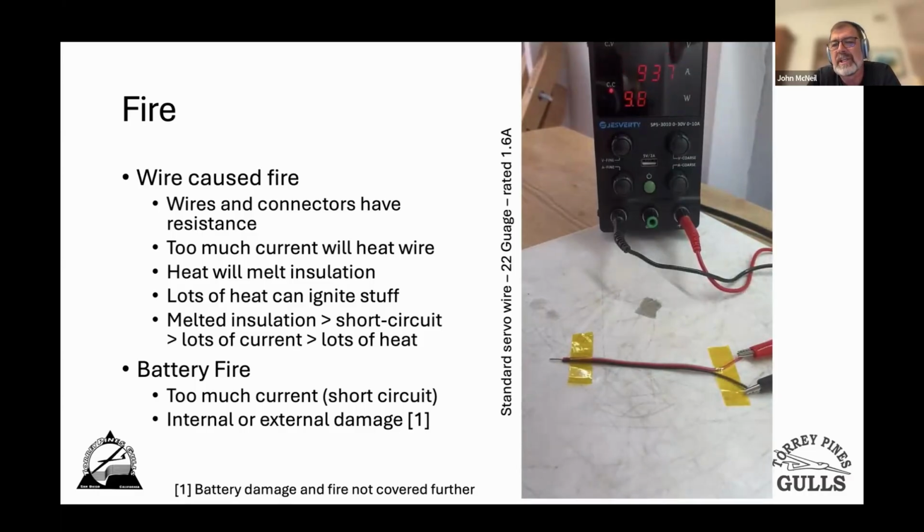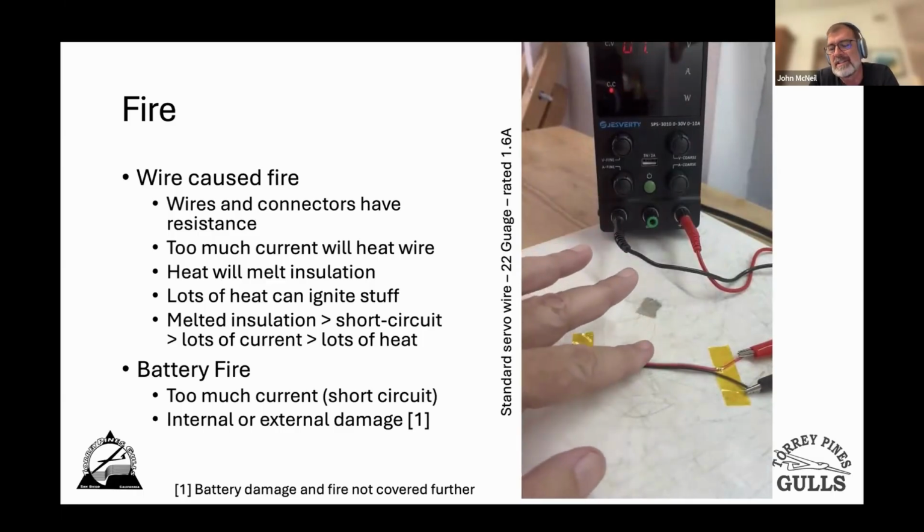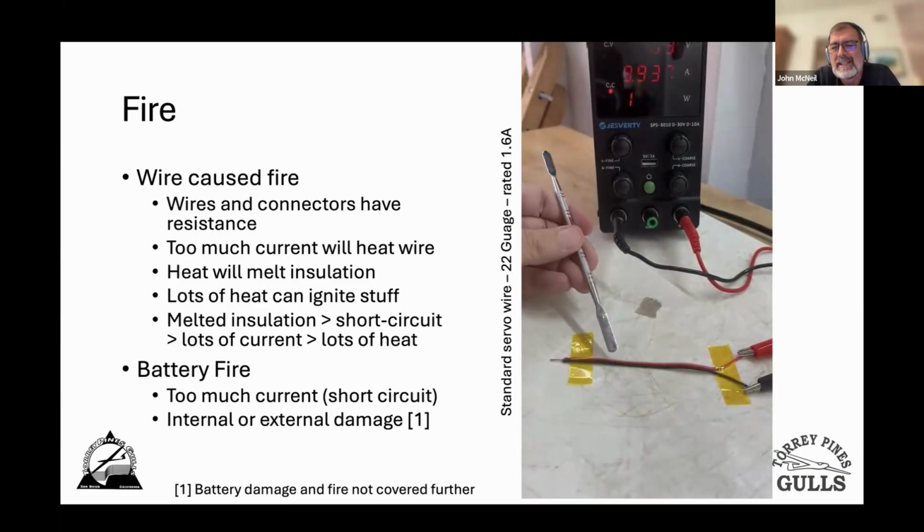Now I can feel it getting warm. I think I'm going to put my finger back on it. Yep, a little cautiously, but I can feel that it's warm. It's not hurting me. But I let it sit here for a while and I've stopped putting my finger on it because you can't see it well here, but if you were there, you would notice that I am making dents in the insulation that are staying. So at 10 amps, this 22 gauge wire is being damaged.